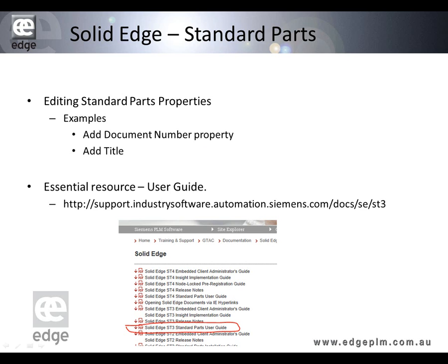One final thing I'm going to look at here is just editing some of the properties on there. I see some questions coming up. I can only get 6 and 12mm. Yes, I'll explain it. The reason is that you haven't added the rest of the libraries. You haven't added the machinery library, and you haven't registered that library. Once you register that library, you'll get a bigger set. You may have thought you'd installed it, but it still needs to be registered. That was on my earlier slide.